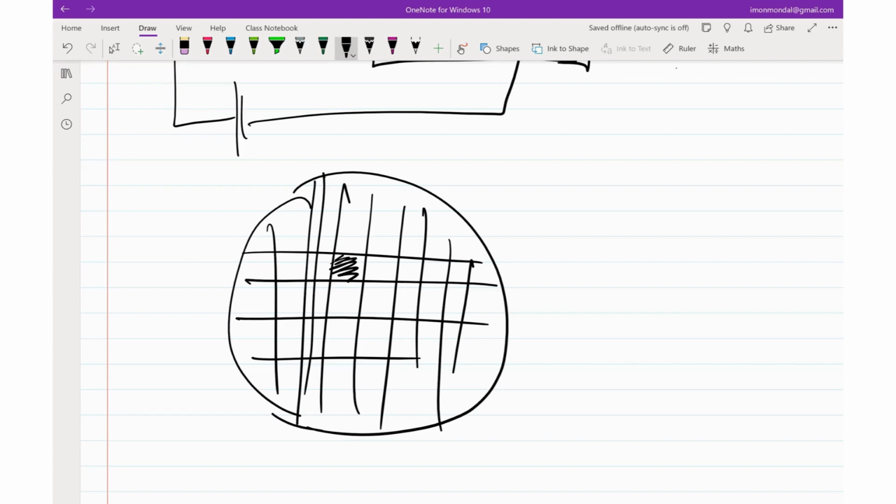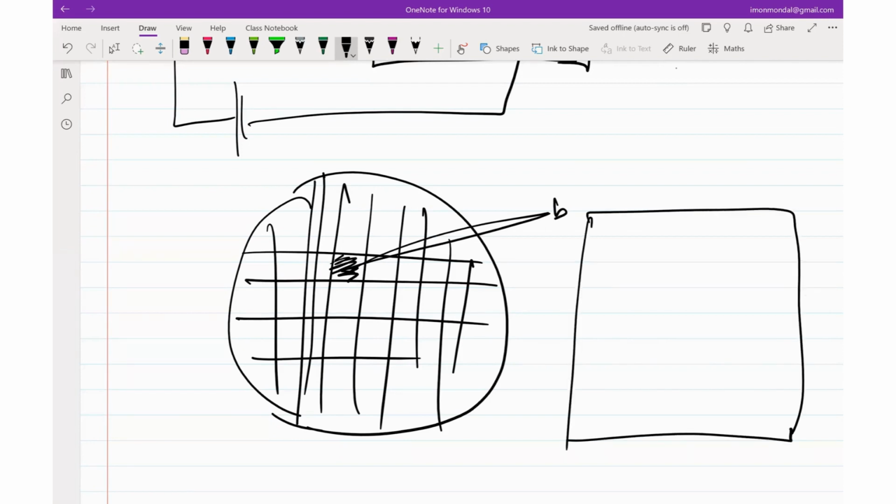But the issue is, each IC is not one single device. Each IC will probably have 1,000,000 devices of their own. Each of them has 1,000,000 transistors. So if I zoom into this entire thing, this is a big piece of square which has 1,000,000 transistors inside. I'm drawing the transistors as squares, somehow interconnected. But let's say you have a transistor somewhere over here, you don't have access to its sides.